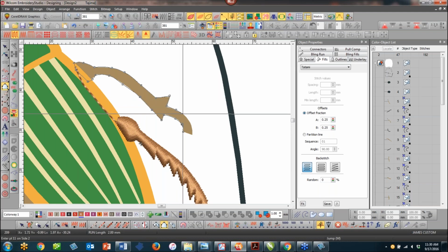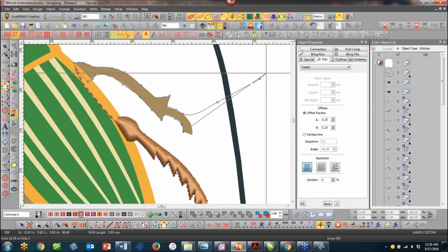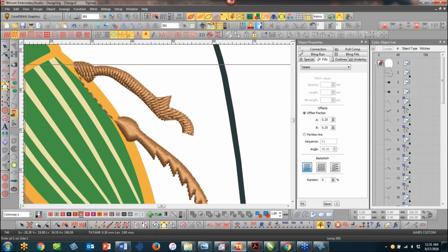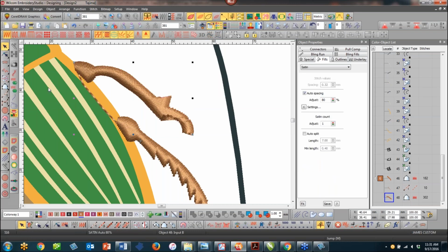just like this. And whenever you make a mistake inside the program, like you go, oops, why did I do that? While you're in the digitizing mode, you can press your backspace key like this. That backspace key will backtrack for you, and then you can come back and complete that just like this. It's not a problem. And even if that doesn't work, you can still go back and just delete it. So here I'm going to press enter. Again, I need to select, finish that right there.